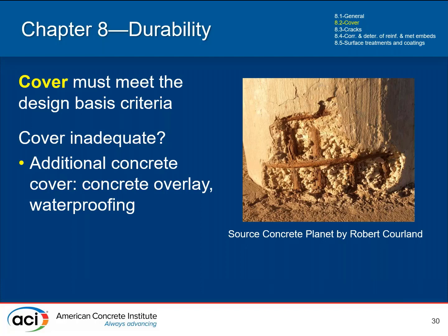If you're dealing with a facade, for example, that has some areas of low cover that are causing it to crack, you can't take the concrete facade and put another inch of cover over the entire structure. That's not feasible. And you also don't want to go in and put these little block out areas on all the areas of low cover so that when you look at it, it looks like it's got warts all over the structure.